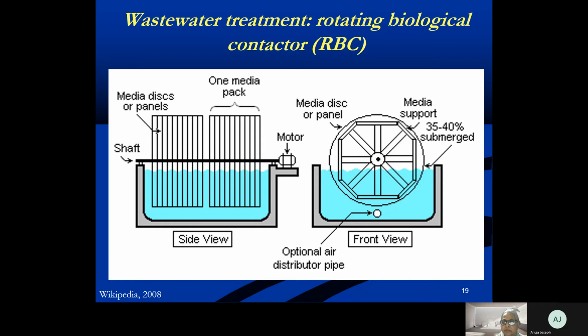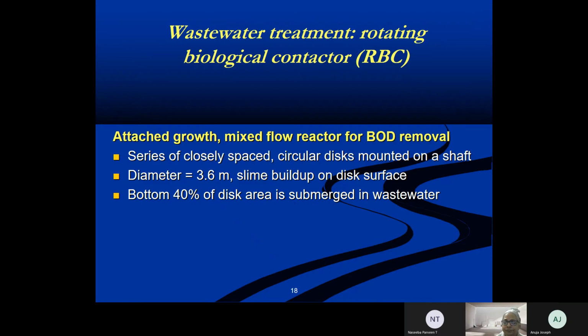It makes more sense, and if they're covered, there is no issue of washing out and drying out and all that. So as long as you make the reactors as closed reactors, then it's fine. But operation and maintenance can be a problem because the stench in these closed reactors can be unbearable. So again, from an operational and maintenance point of view, that's a major issue.